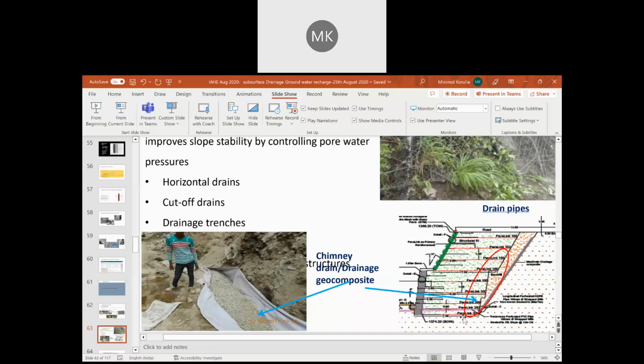And the only thing, as we talked, is the drainage composite, whatever we are using for this type of fin drain, we have to take care of its capacity and performance under different pressures, whether it is 100 or 200, whether it can retain its shape and it can perform. That needs to be checked. The manufacturer or the supplier should give the technical data sheet with the relevant tables and curves. So we were talking about IRC 34 fin drain and French drain.